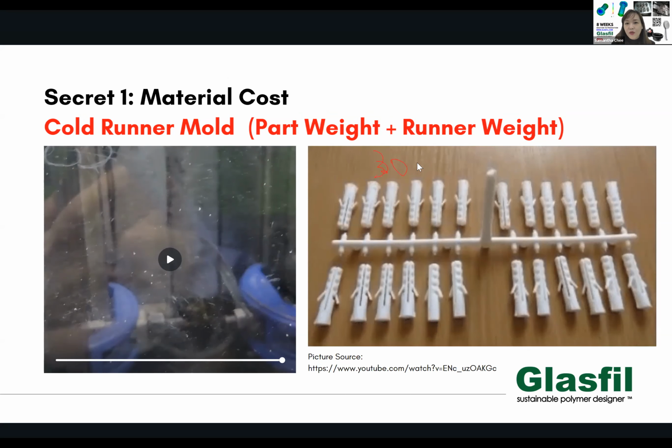So typically, a plastic injection molding cycle time for this part is probably 30 to 35 seconds. What does that mean? That means in 35 seconds, 24 wall plugs will drop. Literally a second and a half is one wall plug. This is the concept about plastic injection molding.